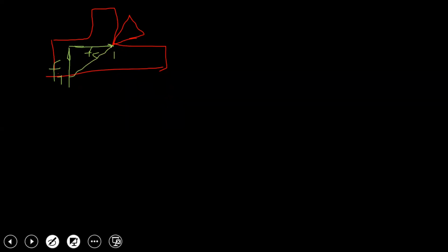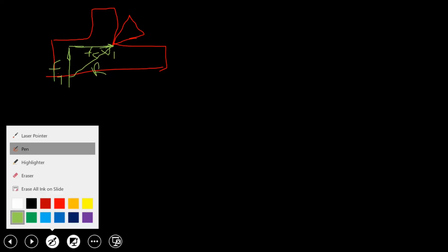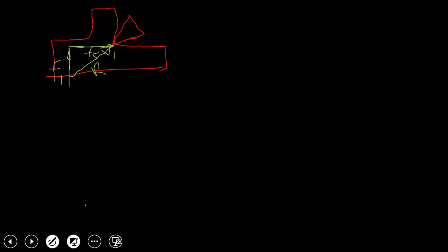And if I calculate a resultant of those two, the resultant will lie somewhere here. Now I will take this resultant as a diameter of circle, look at the midpoint and construct one circle. So all the endpoints of the forces will lie on the circumference of the circle. So this we did for the Fc and Ft.